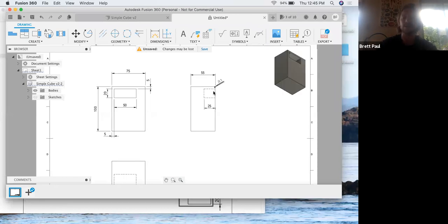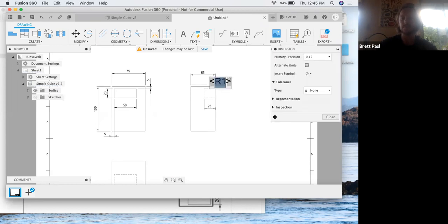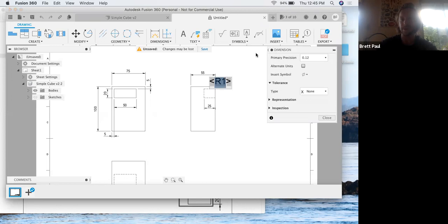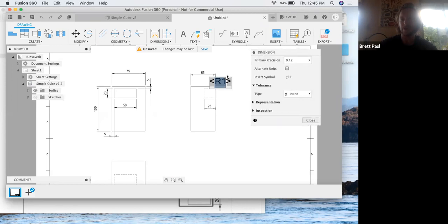Where was I? Radius. So it's all the way around the perimeter, and we want to make that clear because we've only highlighted it on one edge here, even though it goes all the way around. So you can go like this. You can double click on your dimension, and you should be able to take your cursor, move it outside the little brackets, and type whatever you want in addition to it. So you could say ×4 for 4 edges, and they might understand what you mean by that.